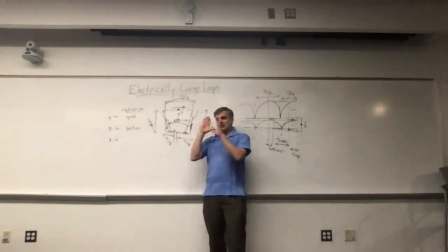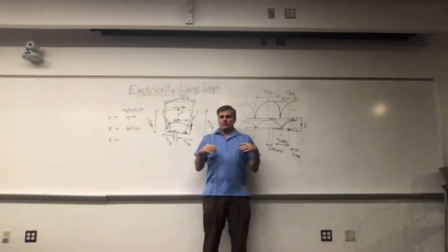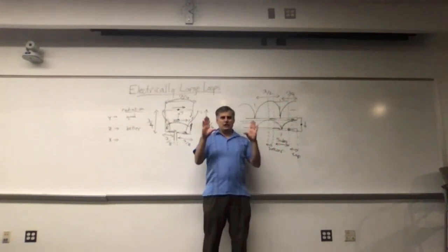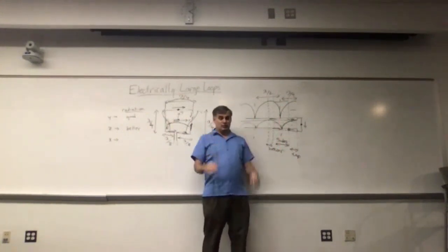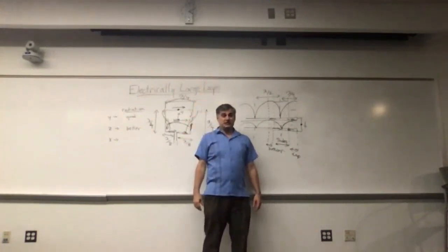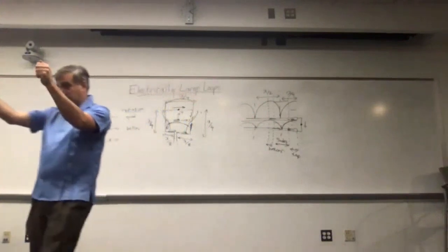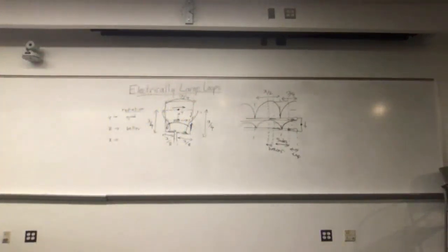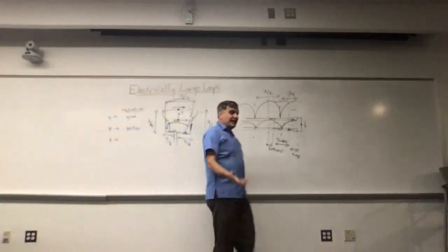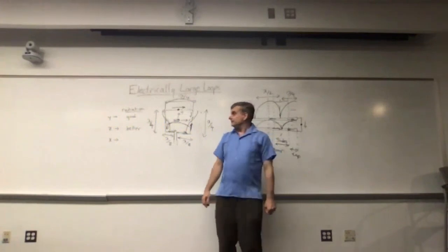But if you steer this null towards the source, and remember your receiver usually has like 60, 70, 80 dB of dynamic range, move a little to the right, move a little to the left. All of a sudden, your signal jumps up 20 dB, becomes detectable again, and you can slowly triangulate where your beacon is using this type of antenna. Now, see, deep nulls have a purpose sometimes for some antennas.